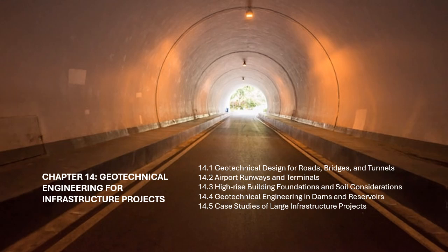Foundation settlement. Differential settlement between bridge piers or foundations can lead to structural damage. Geotechnical engineers design foundations to minimize settlement and ensure that the bridge remains level over time. This may involve ground improvement techniques, such as soil stabilization or deep soil mixing, to enhance the foundation's performance.